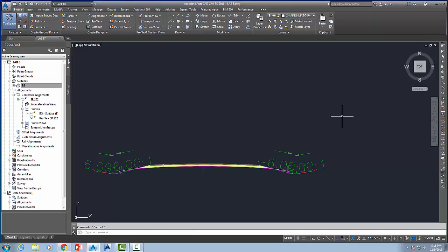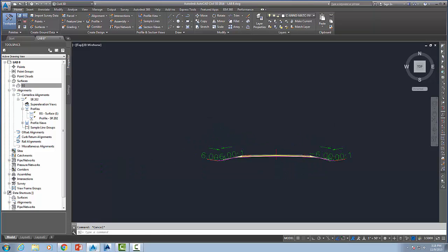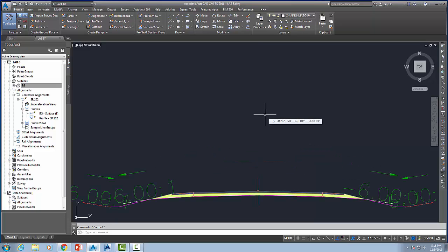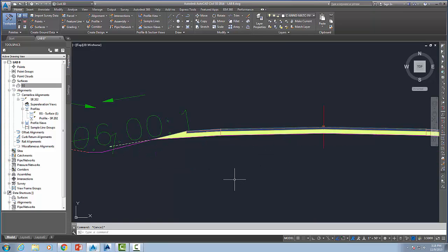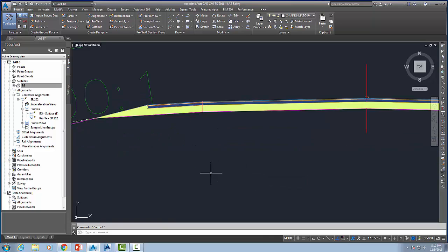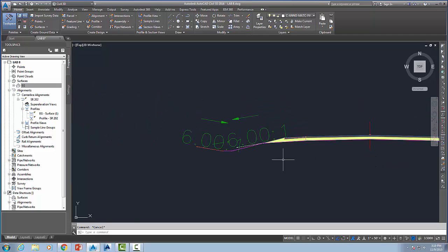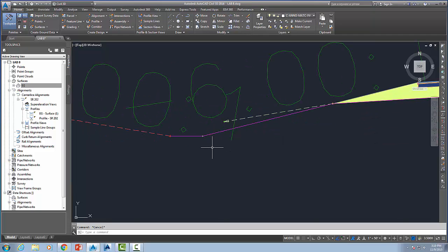So there's our subassembly. So what we're going to now do is generate a corridor based on these different types of things. And one thing I want to mention too, these subassemblies can be really involved in terms of the fact that we have not only a centerline attachment point that's following a profile and a horizontal alignment, but you can also have things like ditches that are traveling maybe at a different profile.